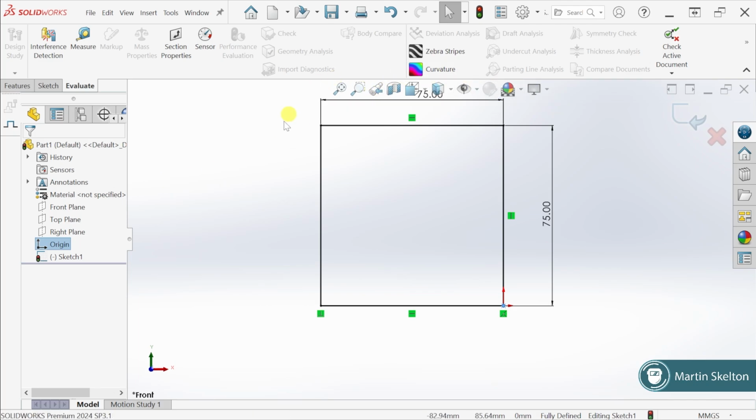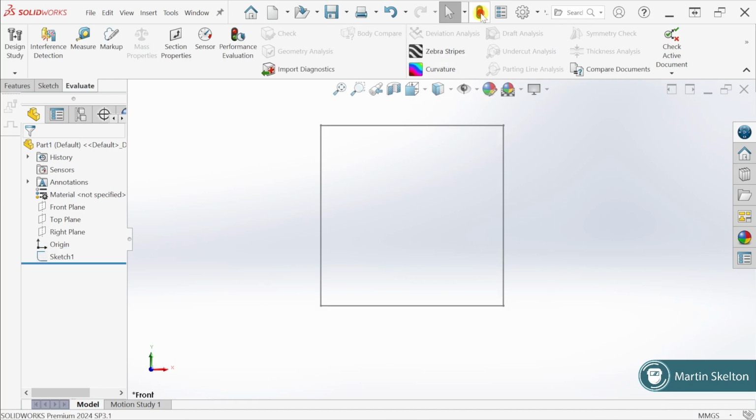Okay, I'm going to add some material here. I'm going to hit my traffic light to rebuild, or you can see it says it's Control and B, or if you want to master one, it's Control and Q. Click, and next my sketch goes grey. See the buttons here have disappeared? So I have no X and I have no back button. Well, that means that I have exited my sketch.